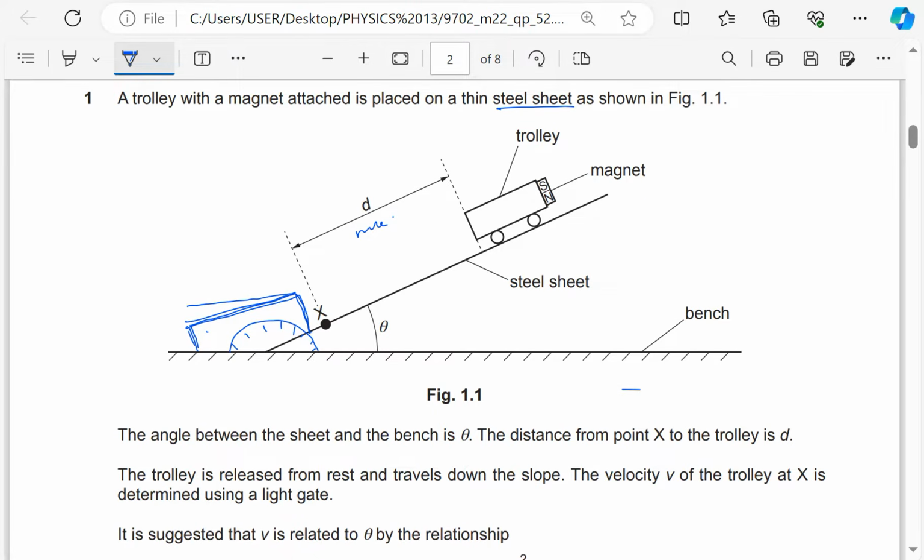Of course, I will have to change theta, so you can use blocks, you can be piling blocks, but if you have experience, you know that I can use a jack or a ratchet, an adjustable ratchet. So to change theta, I may use a ratchet. In my mind, I know I will put a ratchet here. Let this be the jaws for adjusting the ratchet.